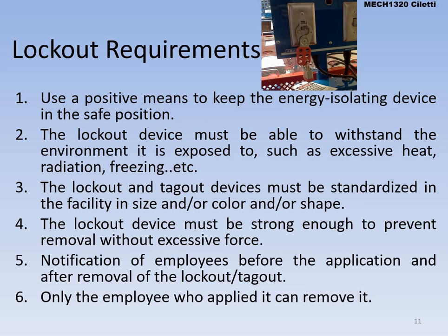Okay, different requirements. Use a positive means to keep the energy isolating device in the safe position. That's why we use a lock and a hasp. That device itself has to withstand whatever elements it's in: excessive heat, freezing, radiation. All those different kinds of elements that it might be exposed to, it has to be able to stay locked in all of those.